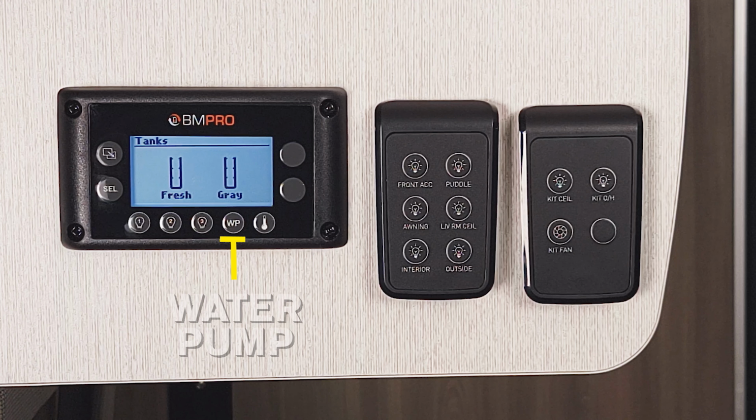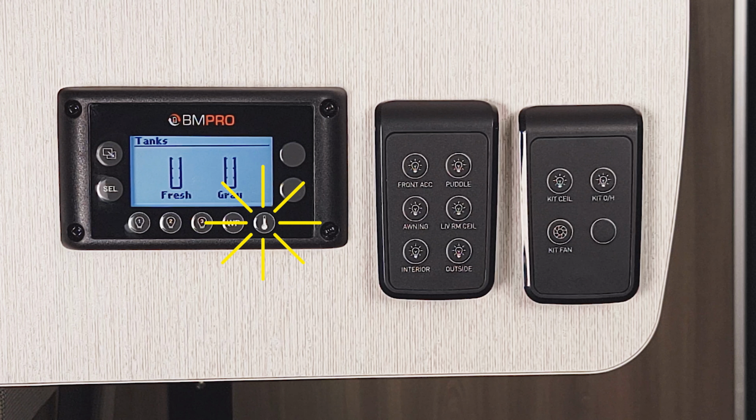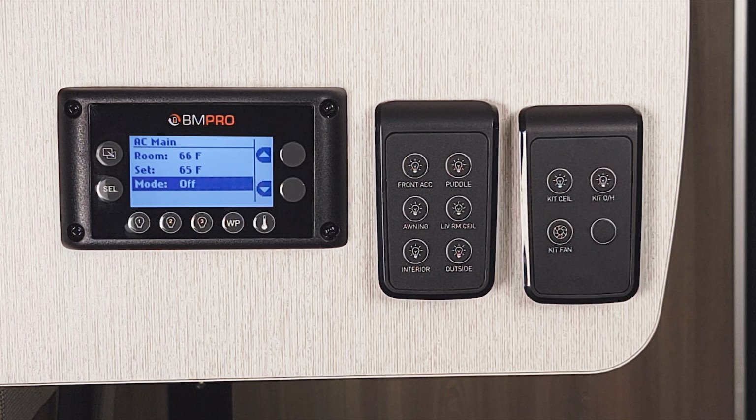The fourth button here turns on the water pump. And next to that is the button for your air conditioner if your van comes equipped with a roof-mounted AC unit. Pressing this brings up the AC main screen. Here we can see the room temp. The select button on the bottom left toggles through the set mode where you can set your temperature. To adjust the temp, you're going to use the buttons over here on the right. Your fan mode selections are off, fan, cool, and cool auto. Then you can toggle to the fan speed and select high or low.